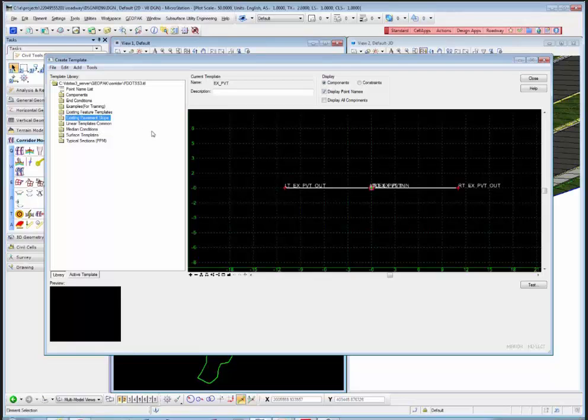on resurfacing projects anyhow. And then we have a new folder here, just like the existing feature templates was streamlined and new. We also have linear templates. Linear templates are really just half templates pushed along a baseline. It could be an edge of pavement line, could be a curb return line, it could be a median line, and you just need to build a corridor off of that one line. So what you see is kind of what you get there.